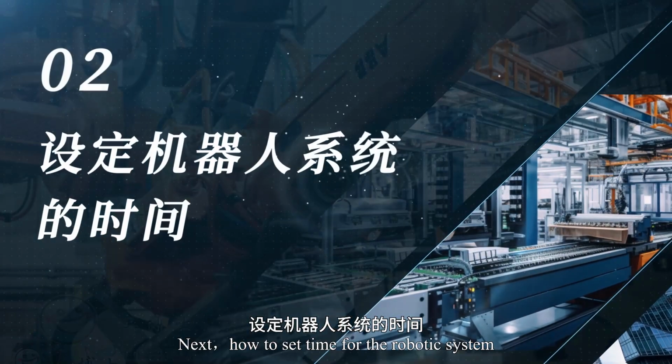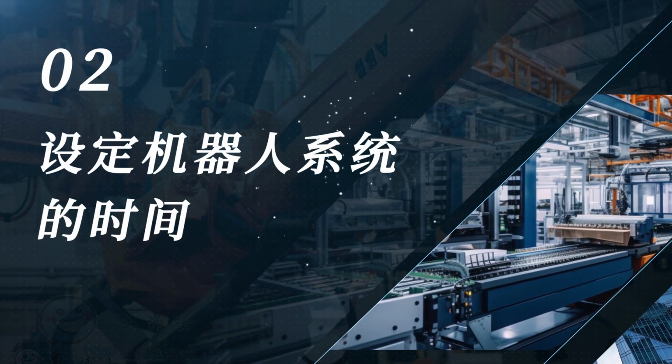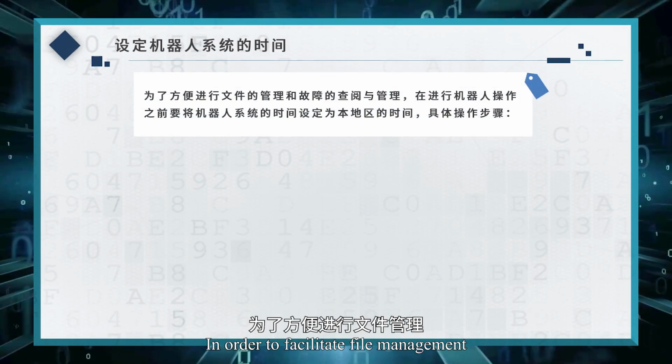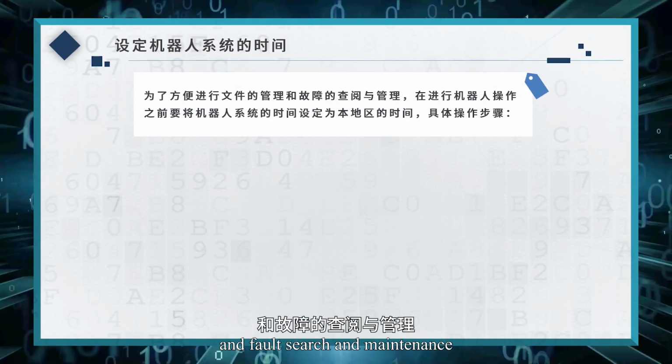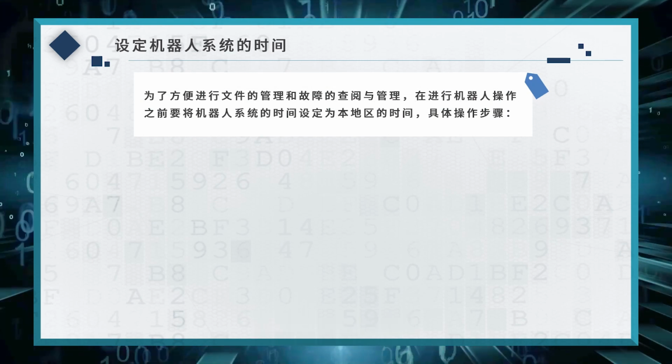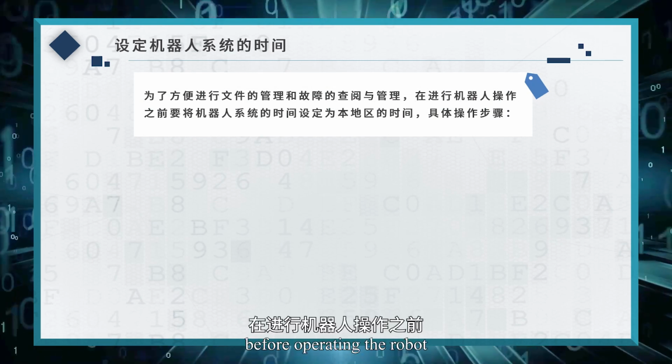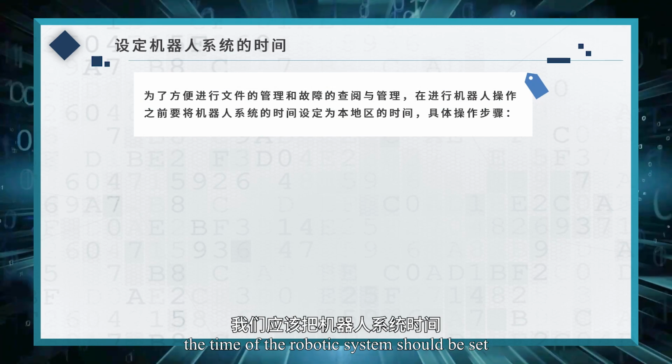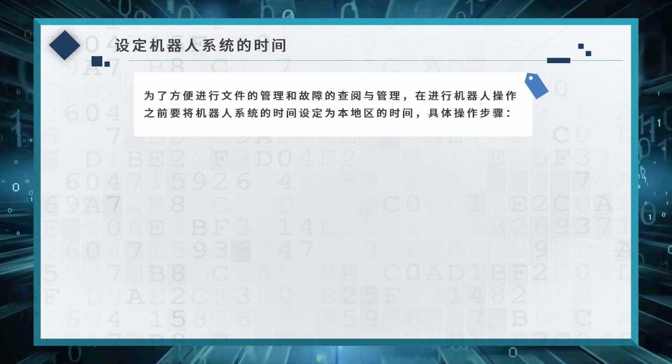Next, how to set time for the robotic system. In order to facilitate file management and fault search and maintenance, before operating the robot, the time of the robotic system should be set to the local time.